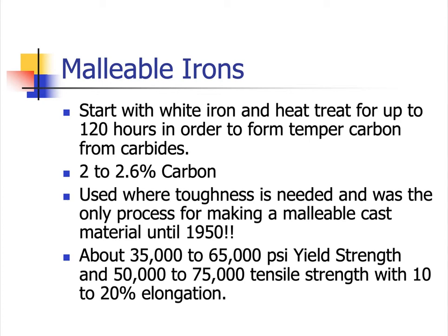So essentially, you're making cast iron, but instead of it being flake shaped, it was more or less round. Okay, so now I got to use another analogy. So if you were to take Grape-Nuts, which is, I don't know if you've ever seen that even, but it's kind of like granola and milk, and you froze that, and you make a bar out of it, and then you pull it in tension. What you can imagine is that those roundish blobs of granola in the ice are going to be less detrimental. They're not kind of cutting the surface or making a crack for a crack to form, and so they're basically going to make your part more ductile.